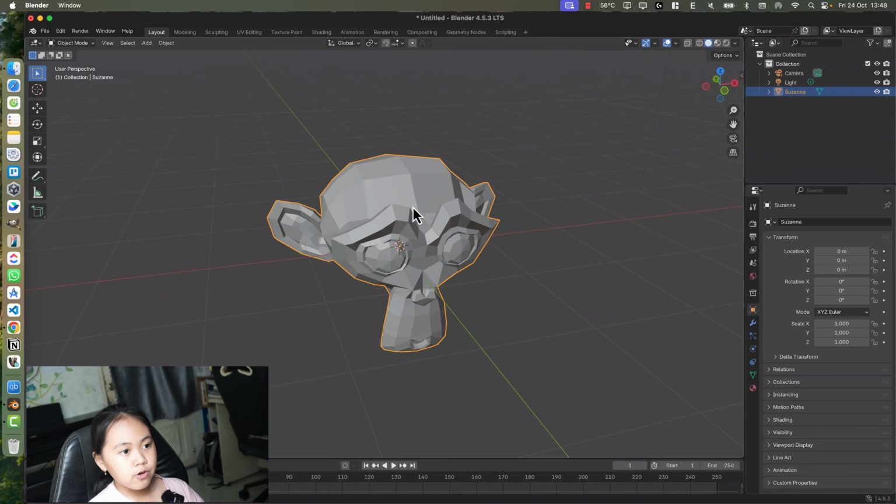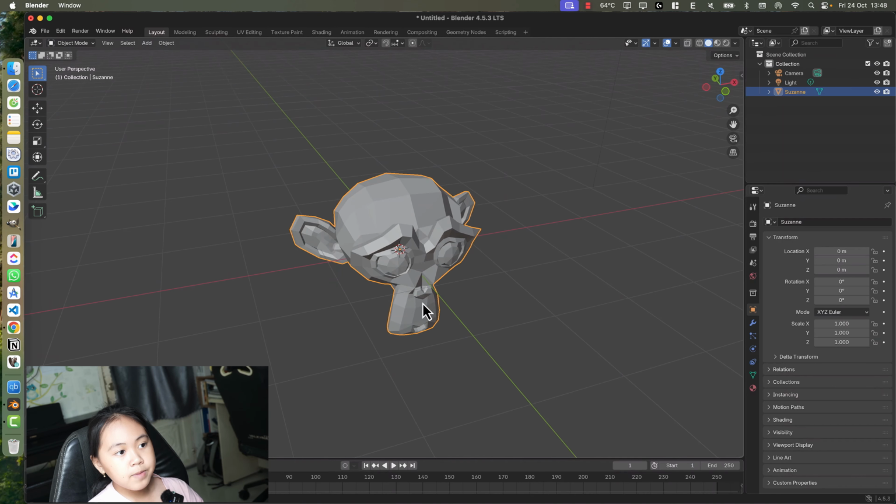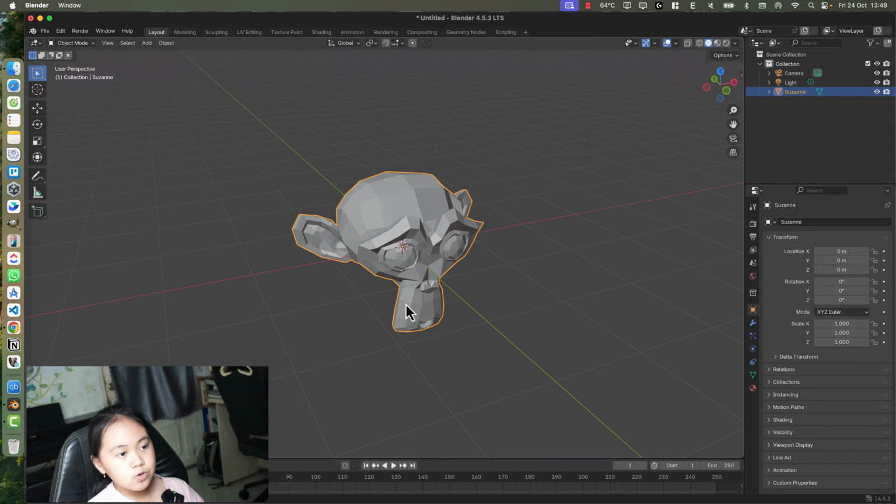So we just learned how to create objects and delete objects. You can also add an object up here in this tab, which works basically the same. But I tend to use Shift A more, one because it's faster, and also I have this search option, which is an extra option when you press Shift A. But for beginners and starters, you should try to use shortcuts more because it just basically speeds up your production. So you don't have to search for buttons, click them, and then confirm.